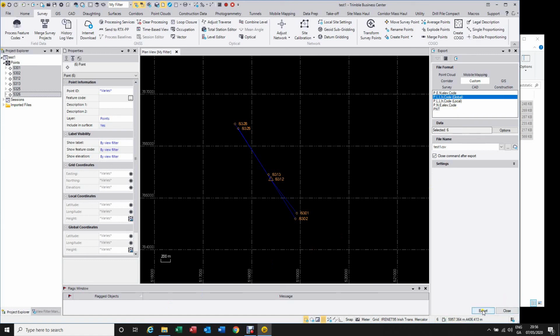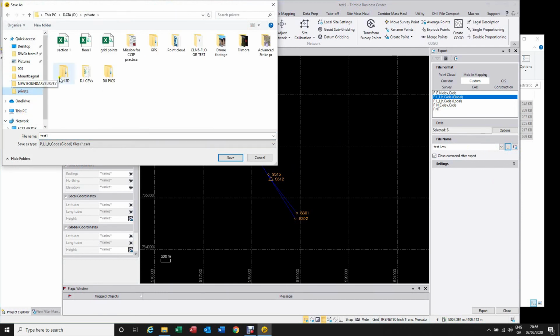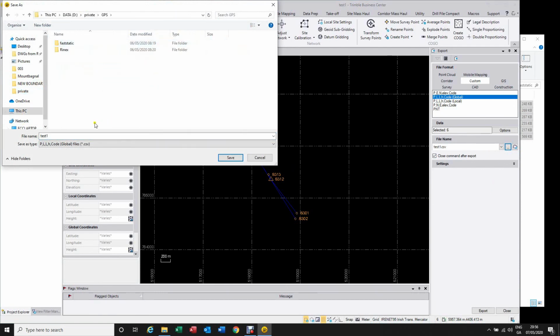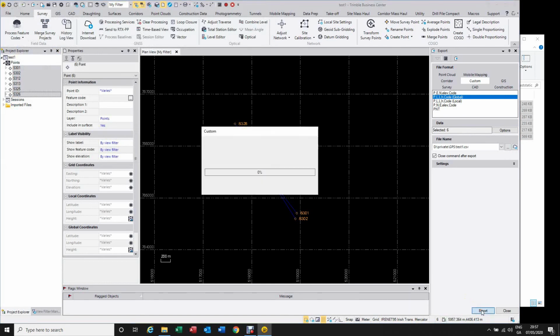If you select this one, export, make sure you have the accuracy, the decimals on precision, long enough. Then when you bring it in, you open a new job, obviously ITM, and you bring in the CSV file, you just pull it in, and you select from the list. Well, let's do it, why not. I just select, and let's do in this one, test one, save, export.